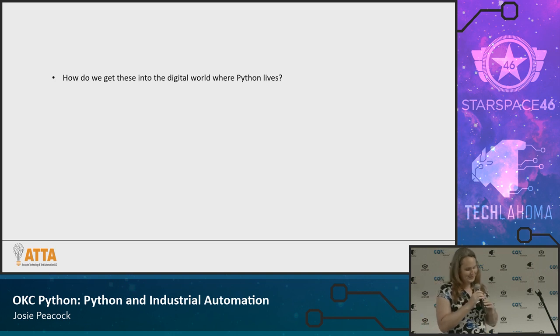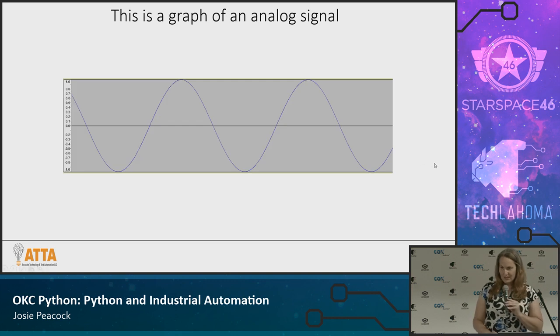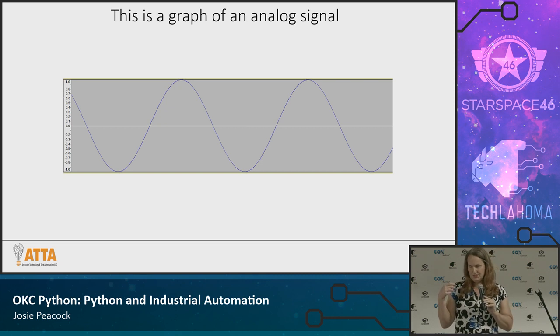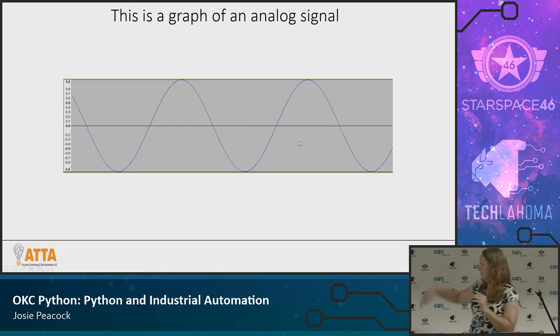Kind of. So we're going to go back here and look at this signal again. Basically, analog to digital conversion is you have an analog front end running at a certain frequency, which is your scan rate, your data acquisition frequency. I've heard it called a lot of different things. But if you had a scan rate exactly the same as this frequency, you would pick up a point here, here, here, and here, and then you get this radically deformed square wave looking thing that's nothing like the signal you actually have.